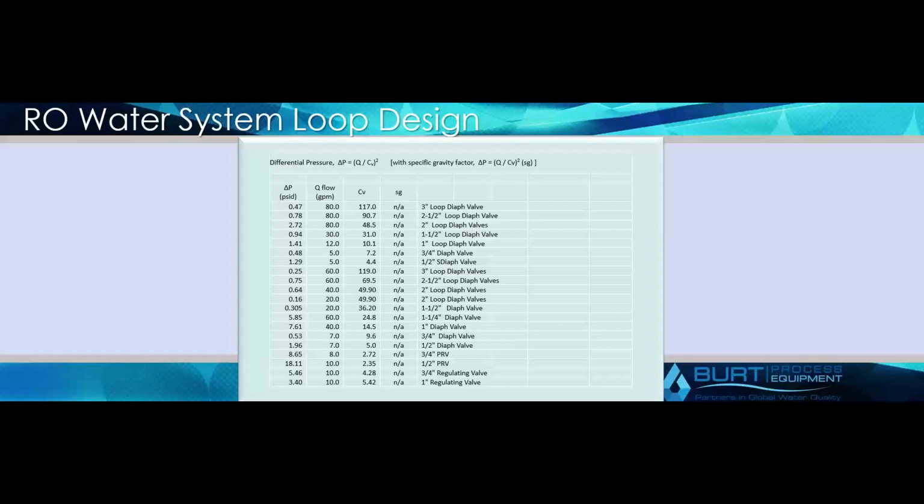So you need X amount of pressure, say 30 psi, at your various processes. Then you have to look at what all the different delta P's are, and this is just giving you an example. Obviously, this is a fairly involved process we're not going to go into in great detail today. This covers 2-inch diaphragms, 3/4 inch, various different valves. And this will vary based on the material that you're going to use, whether that be stainless steel or thermoplastic in this case.